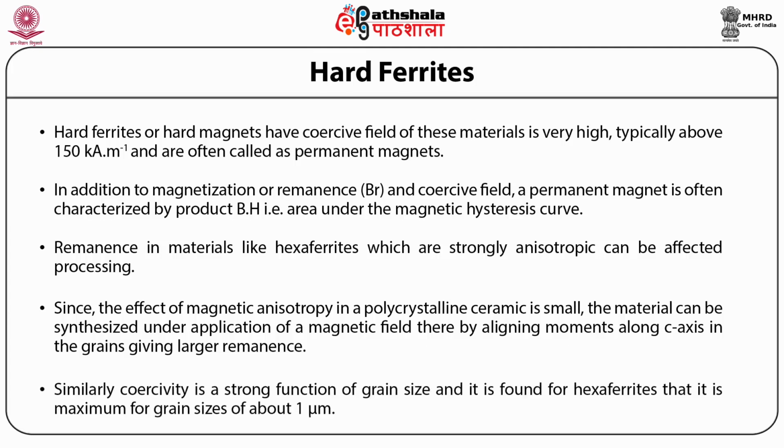Similarly, coercivity is a strong function of grain size, and it is found for hexaferrites that it is maximum for grain sizes of about 1 micron.